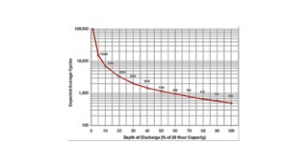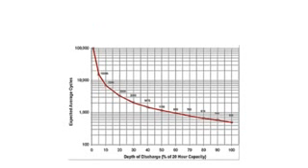One can set a voltage at which the output from the battery can be switched off based on a particular battery voltage. In the industry, the term DOD or depth of discharge is commonly used. Battery bank therefore should be designed above the capacity for which the battery backup is required. For instance, if for a fixed power output 2 hours of battery backup is needed, then the battery bank should ideally have 3-hour capacity for the same power.